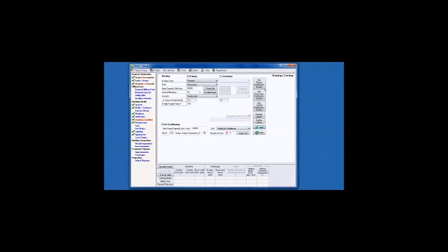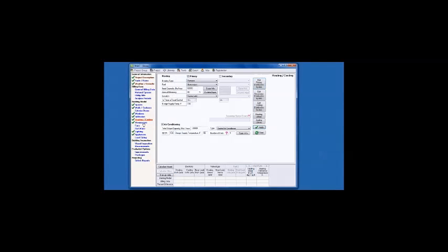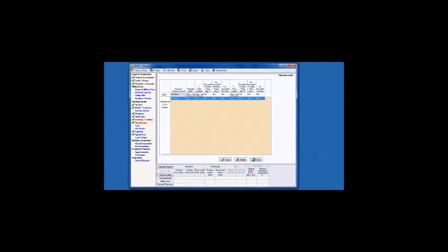There are smart defaults about your distribution system. They're put in the attic based upon the information you put in the previous screen. You might change these inputs, but the defaults are pretty reasonable. If you're doing duct testing, you probably want to update the duct leakage numbers to reflect what you actually measured. The thermostat defaults to 65, heating only. These are pretty easy settings you can probably get from the homeowner to update.